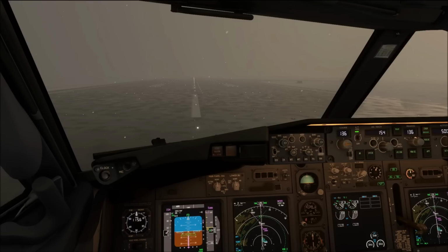And startup procedure, just a quick reminder, the Boeing Supplementary Procedures section in the FCOM 16.10 states a 30-second run-up is highly recommended wherever possible. However, no minimum time is stated, and the takeoff roll may begin once stable operation is confirmed. Do note, the lower display unit should remain deselected when initiating the static engine run-up.